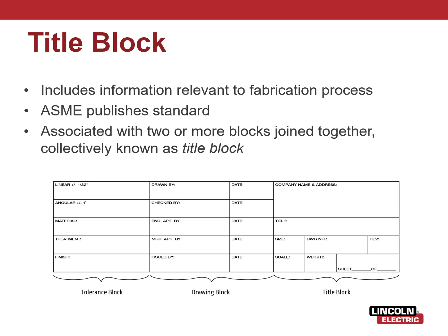Size and scale, which references the drawing itself and the sizes for the paper, which we'll get into in the next slide. Drawing number, just for organizational purposes when you're filing these away. The revision number or a letter, and then sheet what of what. So this could be sheet 5 of 300, or sheet 1 of 1. And the weight, if you have that information.